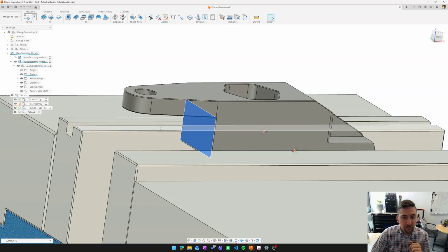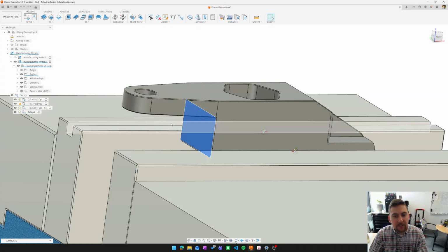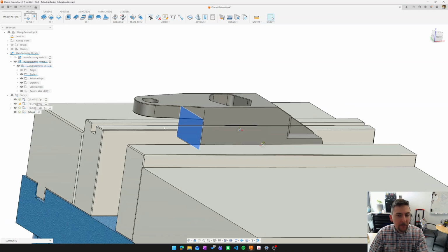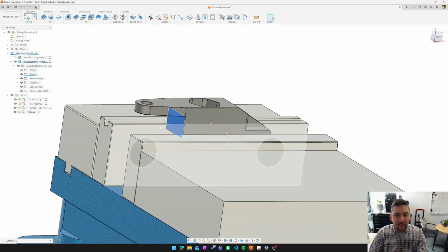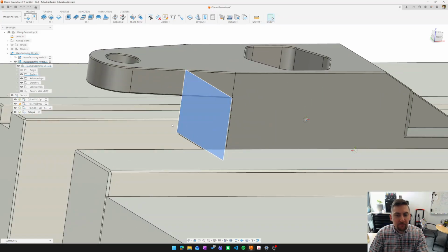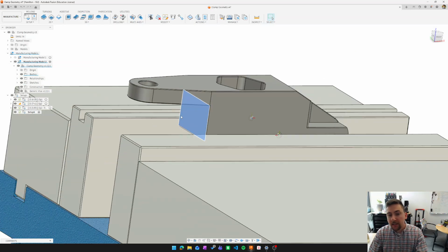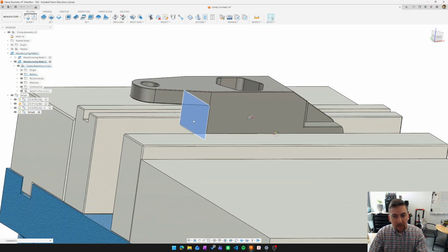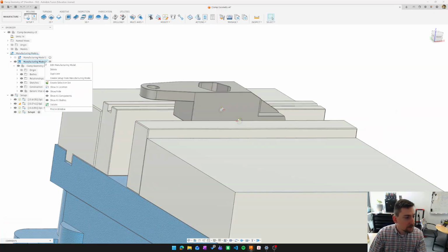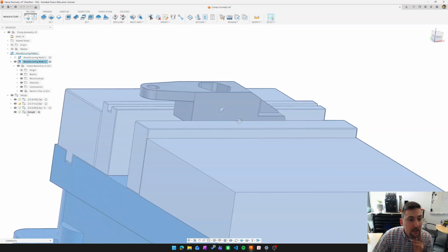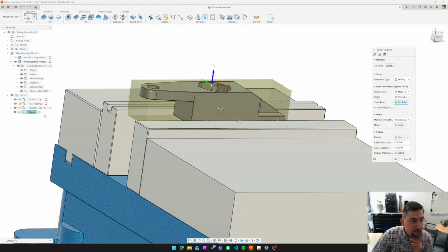So what this means is we're going to need to add in a vise stop within this channel here, and we'll butt up this surface against that vise stop. Now, in Fusion 360, to be able to set that as our datum point, we need to make a couple modifications here. And the good news is we can do that within our manufacturing model. So let me show you the issue here.